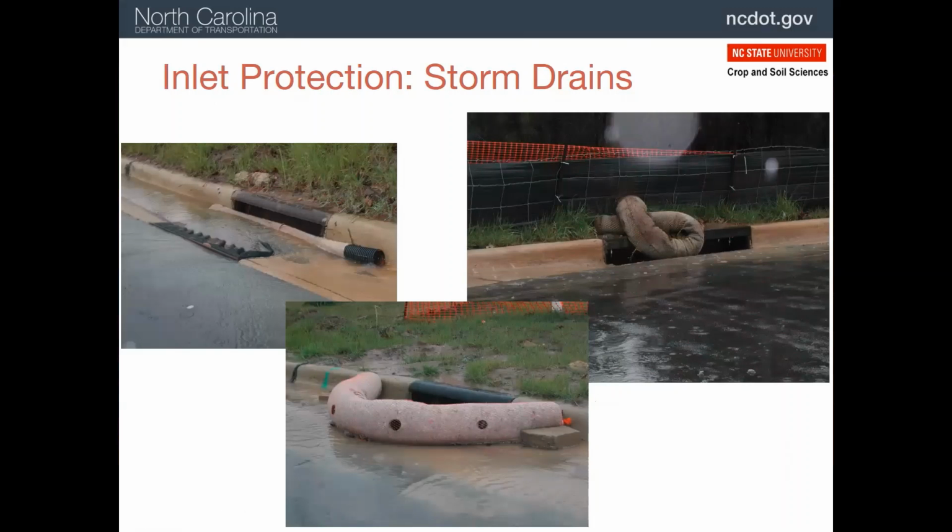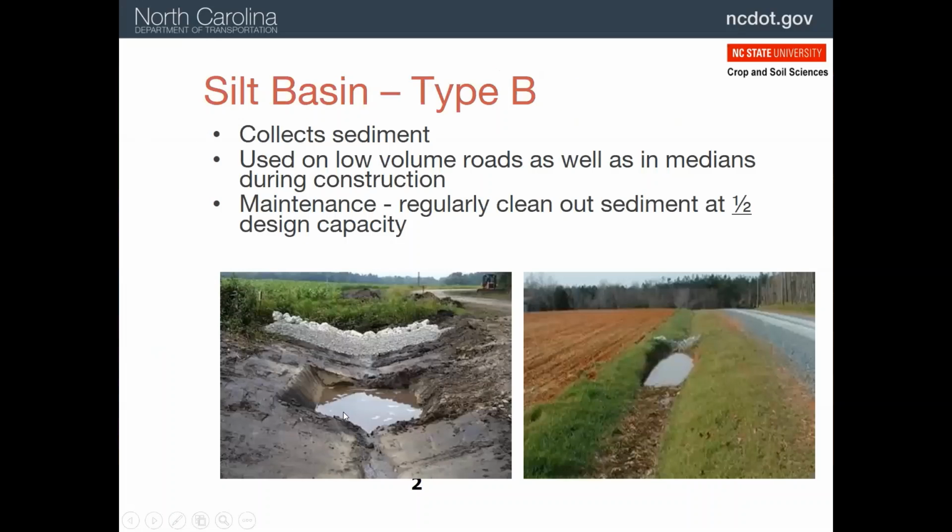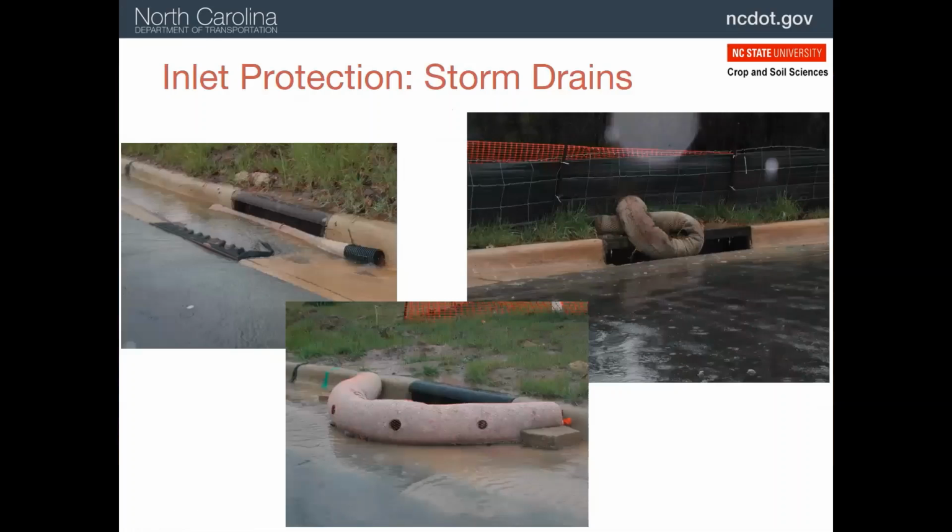If your project involves roadway storm drains, these will also need to be protected if there is still bare soil on the project. There are many types. Some are inserted under the grate, as you see here. Others impound flow on the roadway, as you see here.